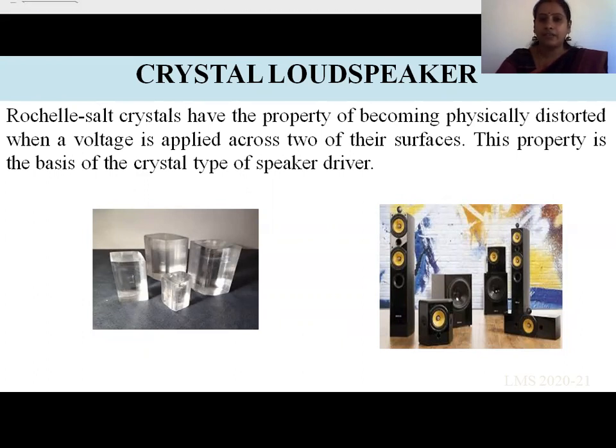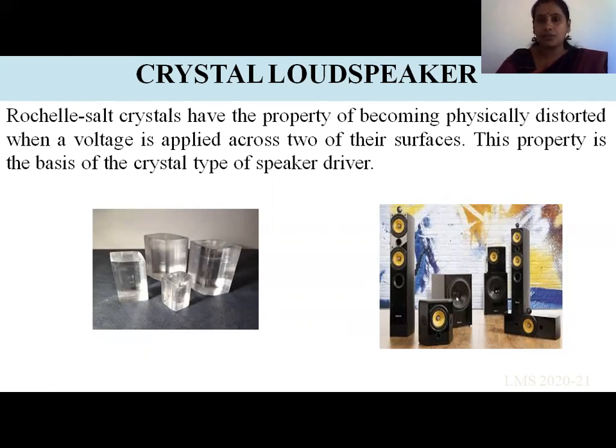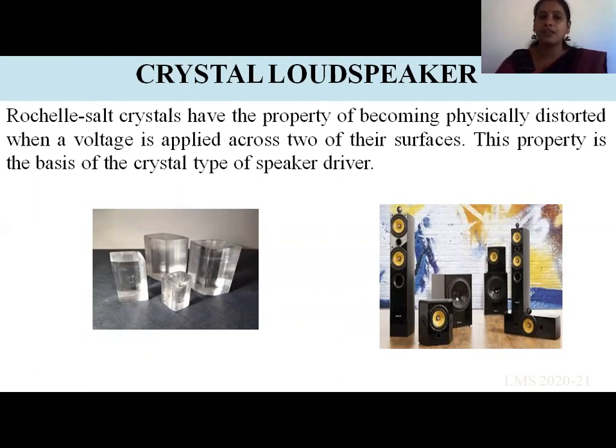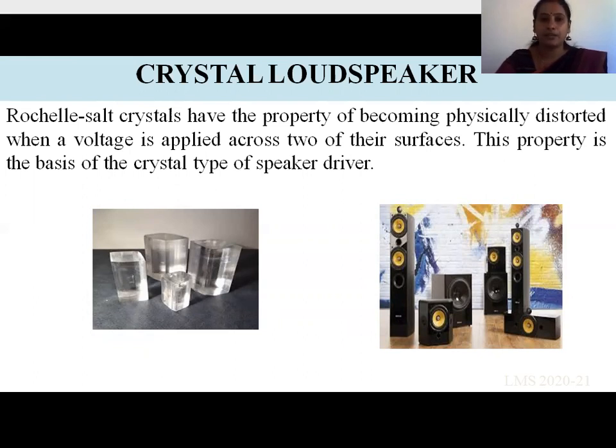To produce any sound waves, the movement or vibration of the diaphragm is a must. This movement of the diaphragm happens in the crystal loudspeaker by the concept of a piezoelectric crystal unit, by which a piezoelectric effect is made inside the crystal that makes the diaphragm vibrate.